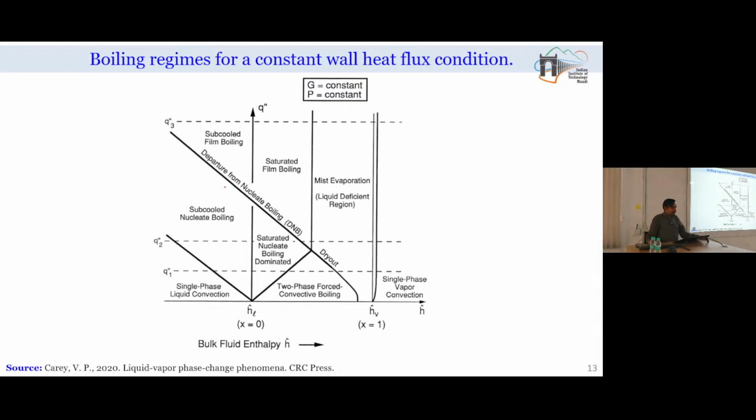Whenever I shift to extremely high heat flux conditions, for example, in the case of the Leidenfrost effect, if temperature is excessively high and we spray some water, it will float over the heating surface instead of wetting the surface and evaporating. Likewise, whenever internally we subject our system to extremely high heat flux conditions, some of the regimes which we studied can even vanish.